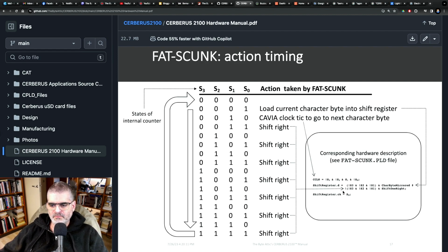In other words, the information in this piece of text is exactly the same information in a schematic in which you are drawing the gates. So you actually have to design everything down to the individual gate and individual flip-flop level, because it's the same level of information. It's just that the form is different.